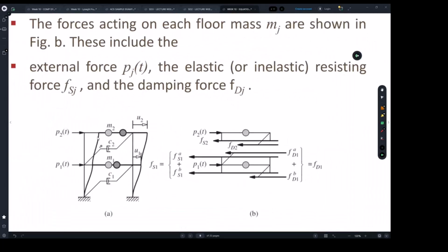What we're trying to take away here is the difference between the second floor displacement and the first floor displacement, because the whole building was moving. So there is actually no stiffness happening within the length H1, right? I'm talking here about the force on the first floor.